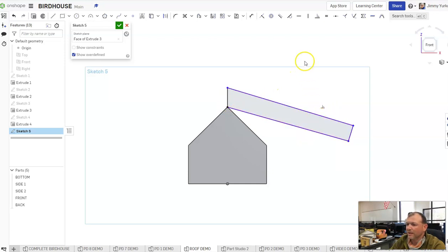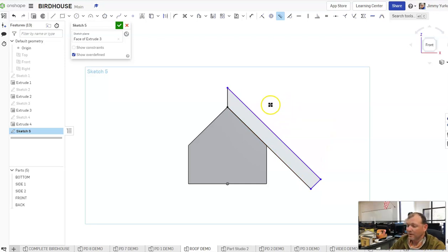So now we're going to go ahead and clean this up. I want to make the sides parallel to each other. I've got three lines, and I need to make them parallel to each other. So tap, tap gets me parallel, and then tap and tap again makes those parallel. The next thing we're going to do is pull this up. It appears that there's already a perpendicular constraint on there. We'll double check, so tap, and that worked fine. So we have a perpendicular constraint at this corner. We have parallel and parallel at those spots. So these lines are parallel to each other, and that guy is vertical.